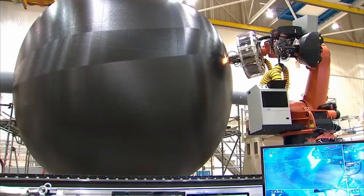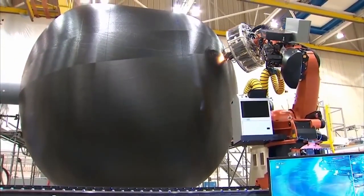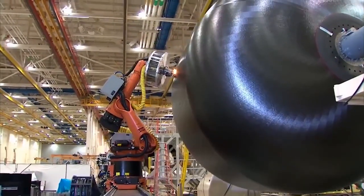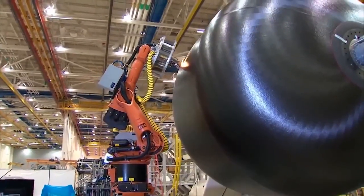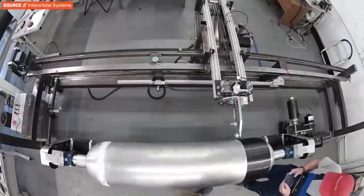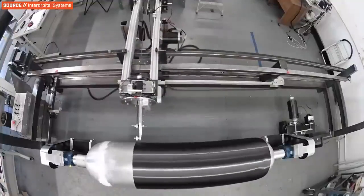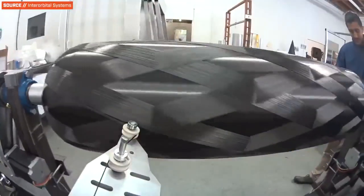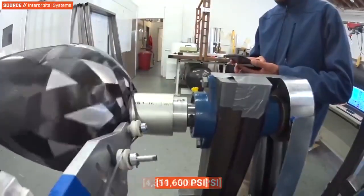At some point, a trade-off occurs where thicker and heavier tanks with higher pressure don't actually pay off, and it's not worth it anymore to pursue a higher pressure in the system. So great lengths go into making tanks hold as high of pressure as possible while being as lightweight as they can. A common method for making lightweight, high-pressure tanks is by using COPVs, or composite overwrapped pressure vessels. COPVs are metal tanks wrapped really tightly with composites, such as carbon fiber or Kevlar, in order to basically keep them from bursting under extremely high pressures. COPVs typically operate at pressures around 300 or 400 bar, but some can get up to around 800 bar even.